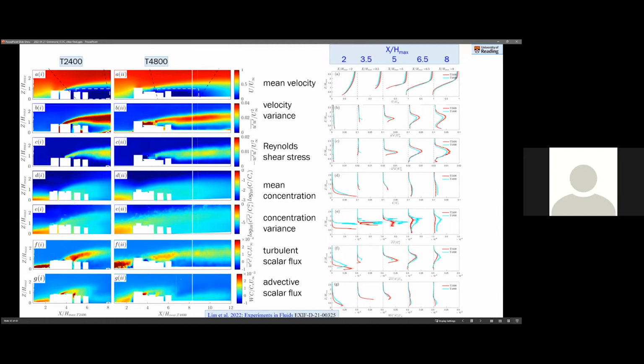We also can take horizontal sections and start to look at the mean profile. Similar to what we were modeling before, we're looking at profiles for wind at particular locations. We can look close to the building and then moving beyond that, we can see that between the 2 scale models we're getting pretty similar results.